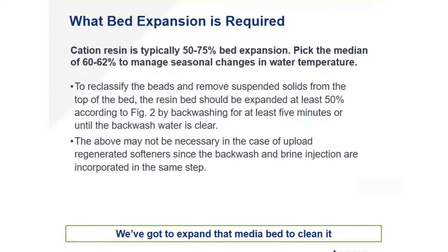The turbidity level or dirt load of that water coming out should follow a bell curve. It should start off clear, ramp up, and get dirtier and dirtier to a peak, and then come back to clear again. You can sample this once every minute in a backwash cycle. I do this with little plastic shot glasses so I can see whether or not I've got a good backwash. That also lets me know if I'm capturing any broken particulate of resin beads as well. I'll be able to see whether or not that unit is backwashing thoroughly enough for its installation.